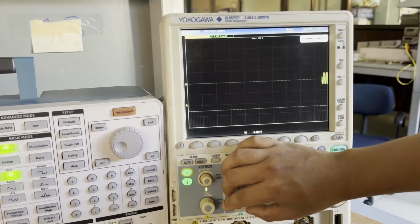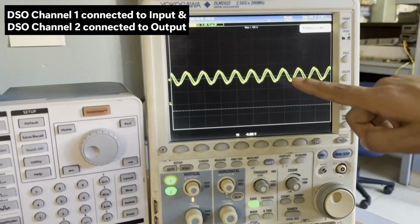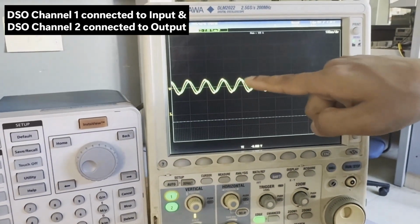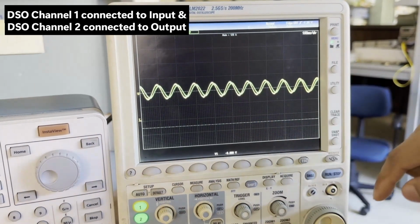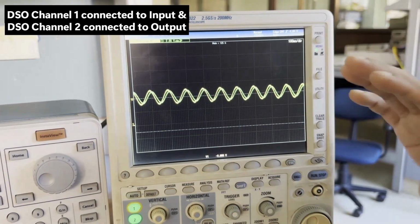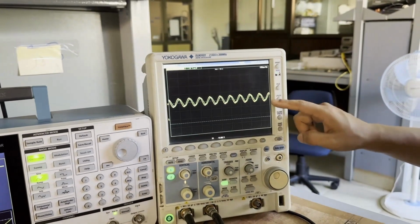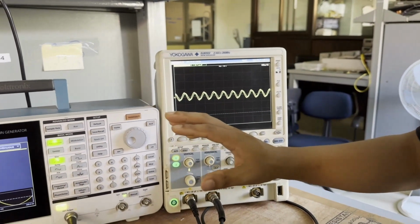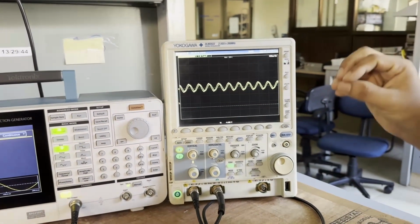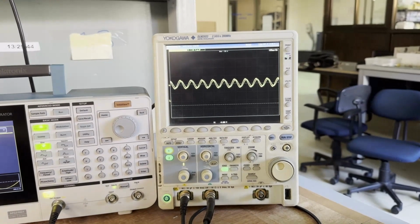Now as I decrease the time scale, here we can see the change in the gain and the shift in the phase between the input and the output. So what we are going to do is log the input and the output data for the various frequencies, and we are going to use the logged data to analyze the frequency response of the system in order to estimate its transfer function.